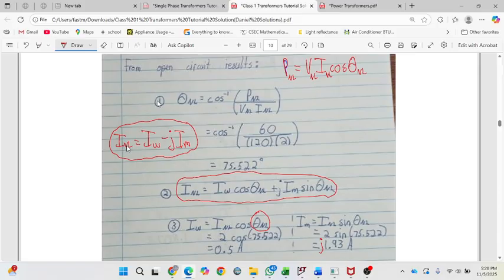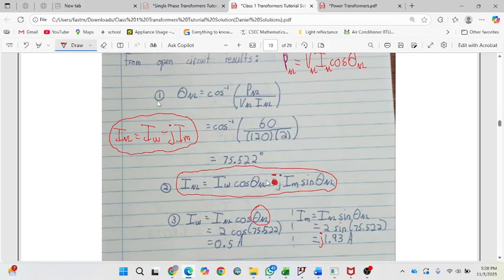But the only time you'll have to do that is if you need to calculate your I1 given an I in. Remember, I1 is your input minus the I no load. So you will only have to do that if you have to calculate I1. Otherwise, you don't have to do that. We just combine these two into that form. I think in your notes you have a negative here, right? We just use a different equation, so don't worry, it's the same thing. Good question. If you're given an input current, you have to subtract your I no load. Input current is not necessarily your I1. Don't make that mistake.